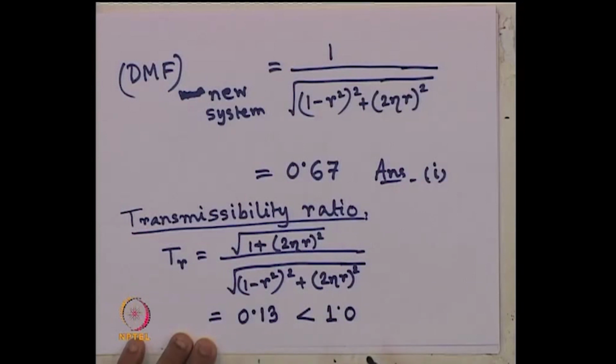So, as a designer I asked you to comment on this. The new system will be very safe, because it is transmitting a much lower force than what it is subjected to, to the foundation. So, our foundation will be very much safe in the new condition also. That is the comment you should provide as a designer at the end of this problem. Fine. So, with this we have come to the end of the solutions for this quiz 1.